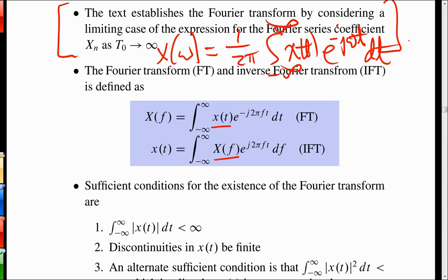So the book that used it for 3205 does omega domain transforms. Okay. Guess what? I like this one better because it's perfectly symmetrical, and I like hertz better than I do radians per second, because communications people deal with hertz, controls people deal with radians per second more. Or at least that's my view. But this one is nice and symmetrical looking. The only thing is you got to carry around this extra baggage of the 2 pi's. But other than that, you've got a nice symmetrical pair.